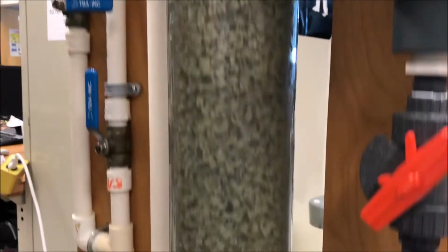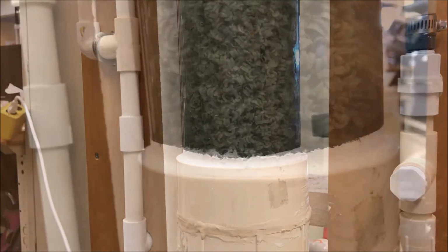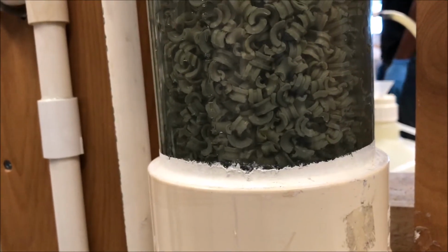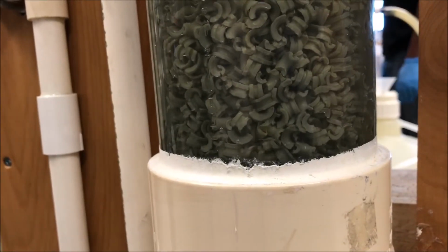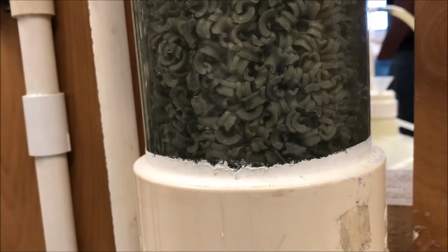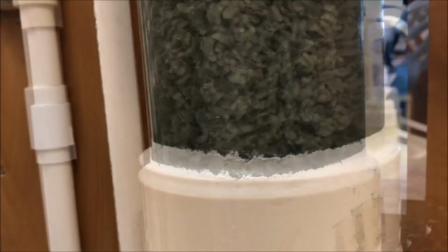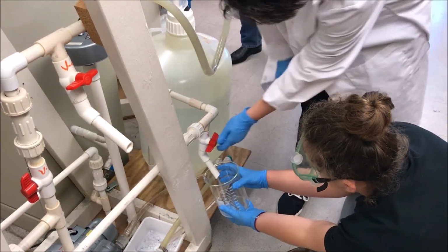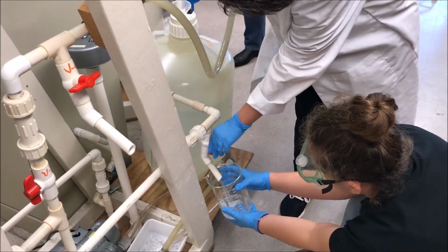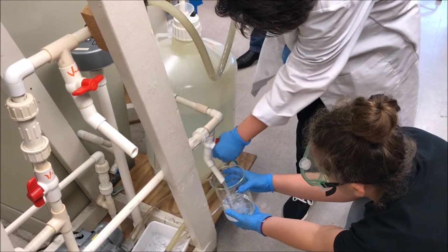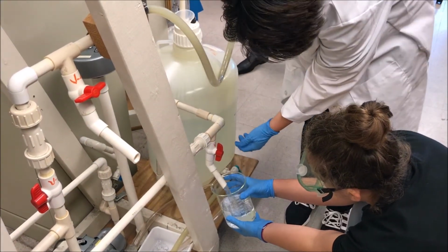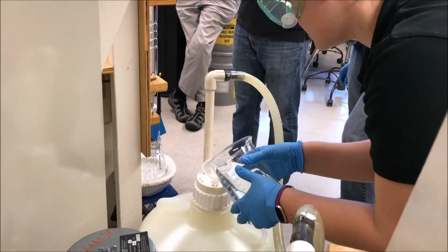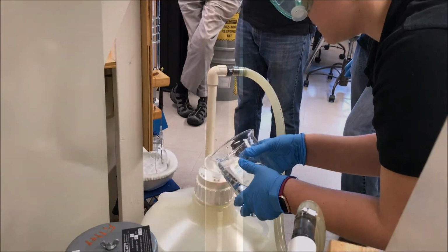Remember the flooding that was mentioned in the beginning? Well, flooding is when the packed column is filled or backed up with liquid. It is caused by excess vapor flow, where the vapor causes the liquid to be pushed up the column. Also, due to the elevation of the column and the exit stream, there may be potential for liquid backup. To prevent this issue, use the purge stream to collect the backed up liquid and pour it into the tank. Doing so will keep the liquid constant in the system.